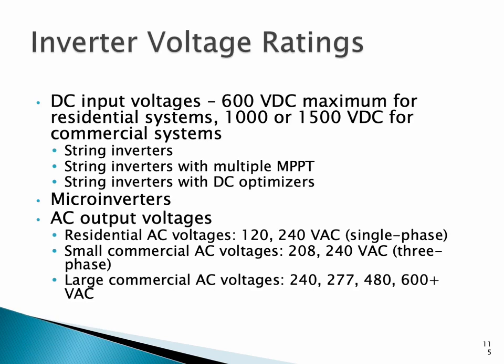We're limited to 600 volts DC for residential systems. We're limited to 1,000 volts DC for commercial systems. And then utility scale ground mounted systems can go up to 1,500 volts DC. So what this means is that I can have longer strings or more panels in series and maximize that voltage, and current stays the same. Volts times amps equals watts. So I can have more watts per string than, say, 600 volts.